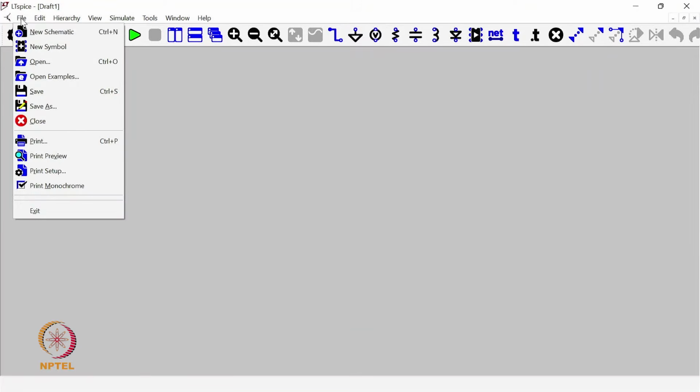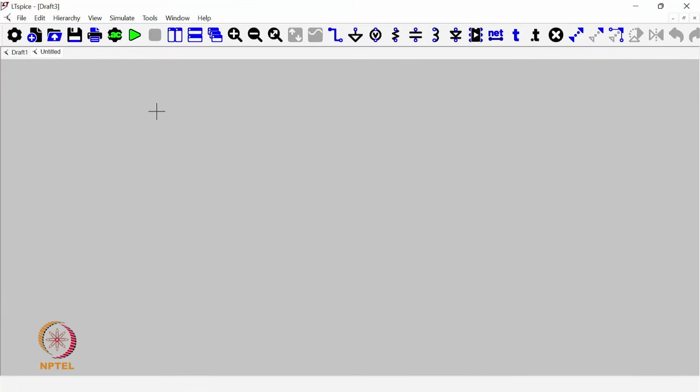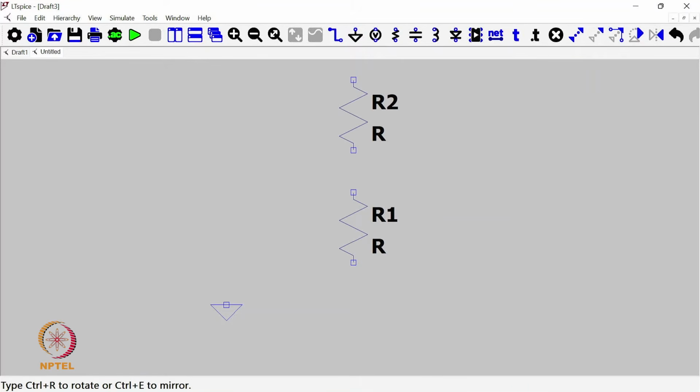So we are going to see now how we do it in the SPICE simulator. So let's make one new schematic and we make some sort of a voltage divider. So we take first the node 0, which is ground, then we take two resistances, R1 and R2.